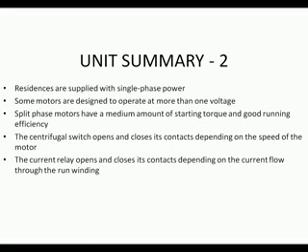Some applications such as refrigeration require high starting torque. Motor components include the housing, rotor, stator, end bells, bearings, and motor mount. Electricity and magnetism create motor rotation, and motor speed is determined by the number of poles. The start winding has a higher resistance than the run winding. The important amperages you need to know about are locked rotor amps, full load amps, and run load amps.